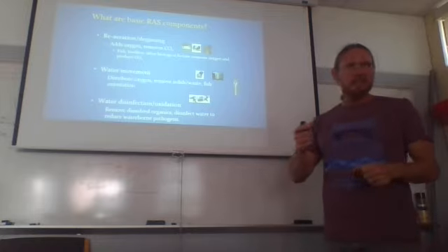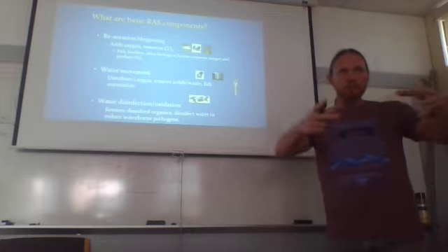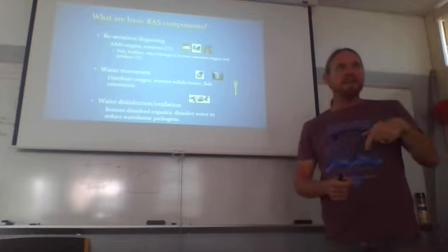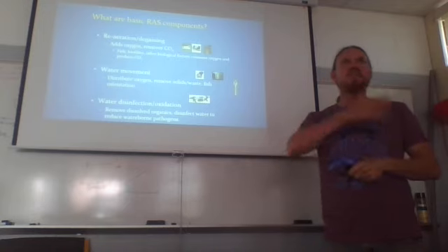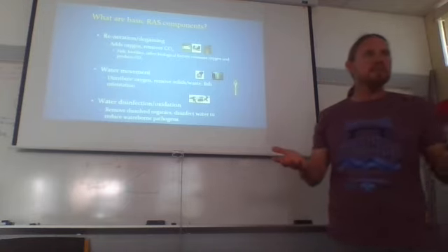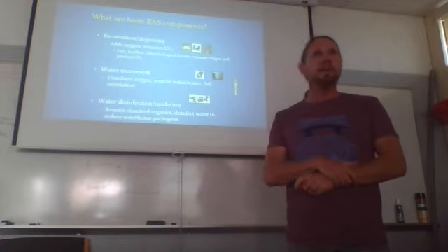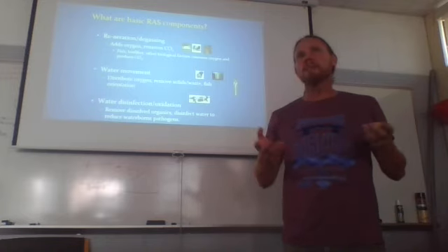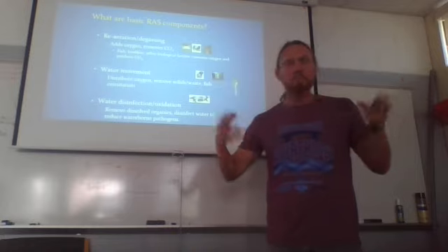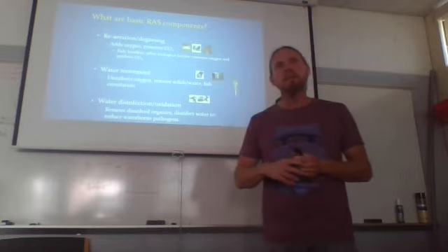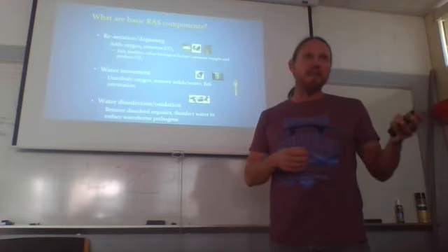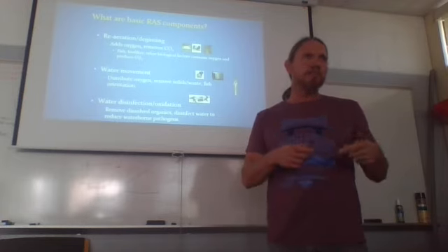But basically what this is, water's flowing through a tube, and there's a tube inside of that tube, a sealed chamber with an ultraviolet light in it, and the water's flowing past that light. The ultraviolet light supposedly is going to kill any little microbes that are in there. But the light loses some of its potency over time. So after about a year, even though the light is still burning and looks brilliant and maybe might still blind you if you look at it, it's not going to be as effective at killing organisms in there. So you need to stay on a strict schedule.